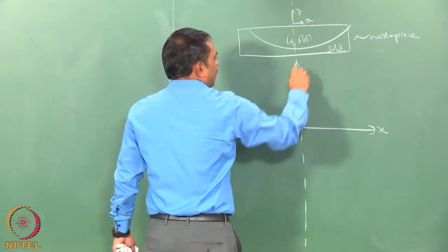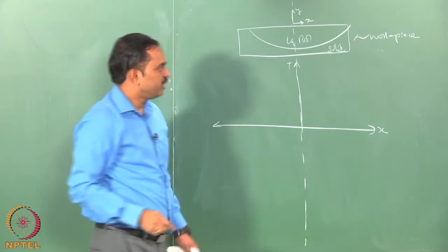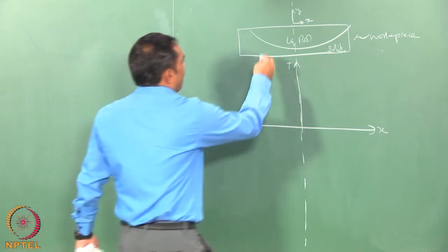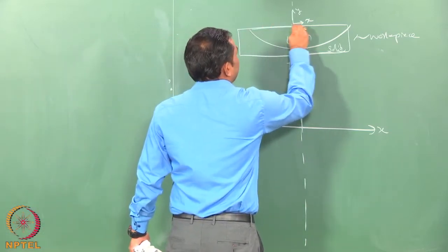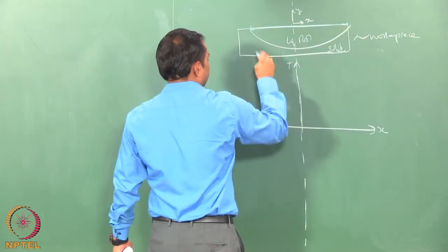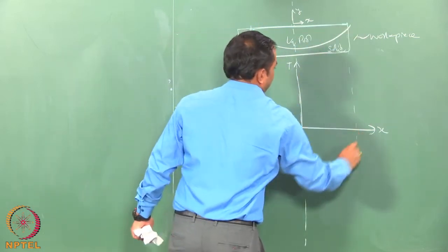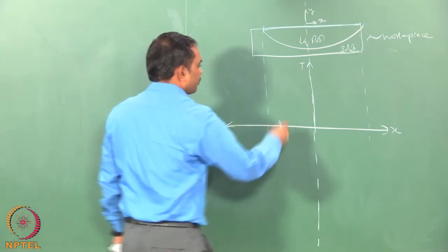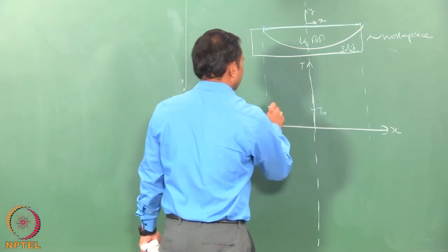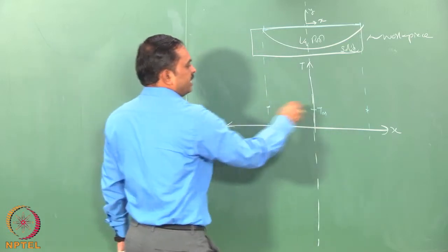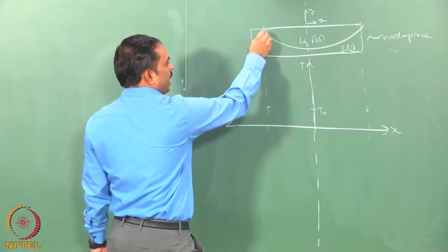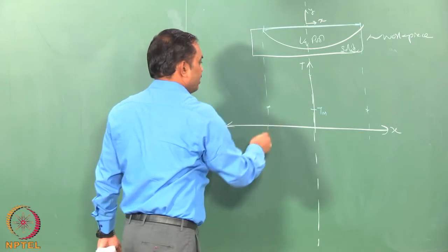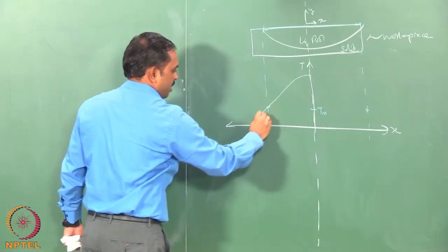let us first plot the temperature. So, how would the temperature look when you go from the center of the pool away is something that we can plot, and that means that I am actually now looking at the topmost layer in this region. So, how does the temperature distribution look like? It looks like this. Here is the melting point. I am putting points here because that is what is defining the fusion zone end, and at the center of the pool you would have the temperature very high. So, you would have a peak temperature like this. So, you would have a temperature profile like that.